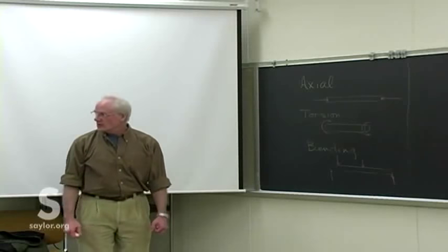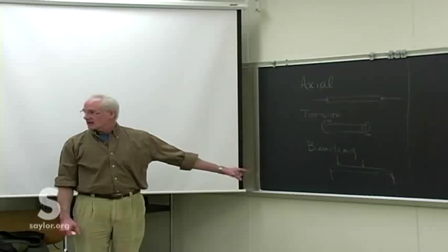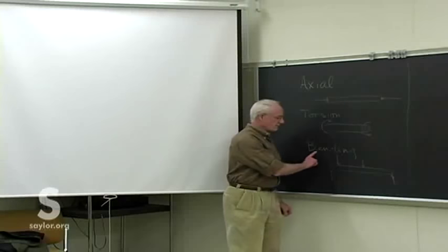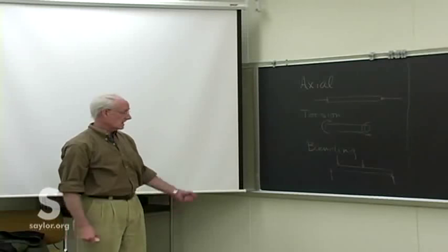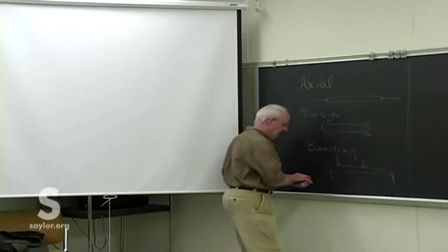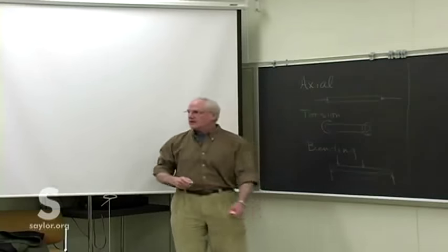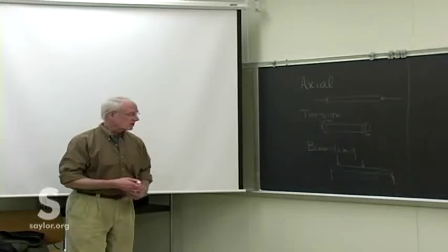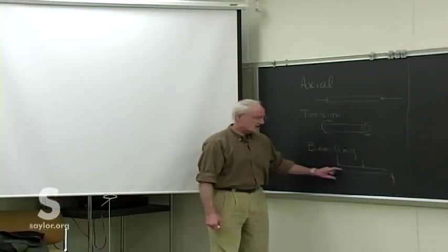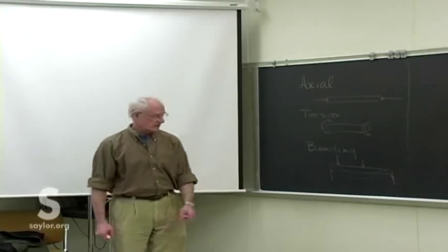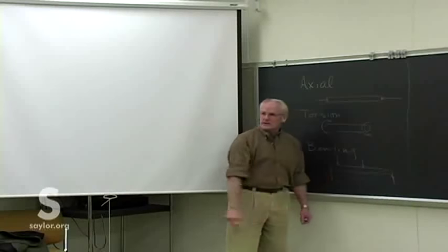What we're going to review again this morning is the shear and moment diagrams we get from that, because what's going to be a big concern to us now is how these beams respond to this kind of loading. It's not any great shakes to know that these are going to bend something like that, but any place you've got a curve in the beam like that, that's internal moment, and we need to look at that. We need to see, can the material withstand those kinds of loads? There's also, of course, shear across here, as well as the internal moments.